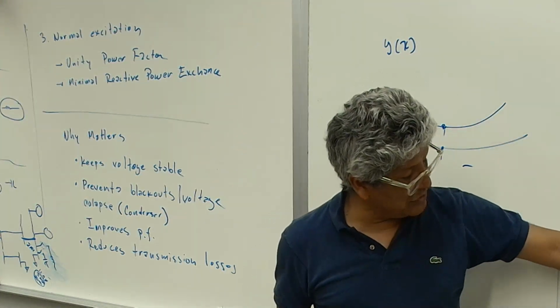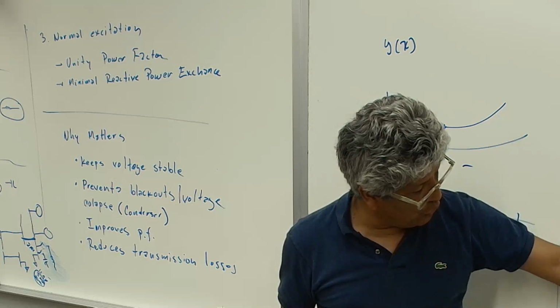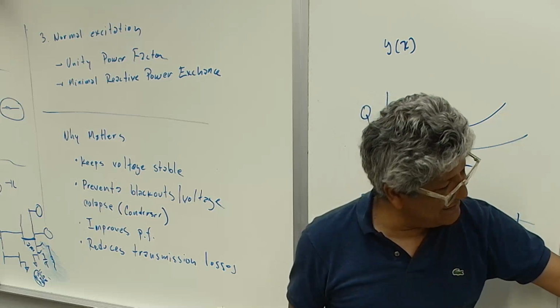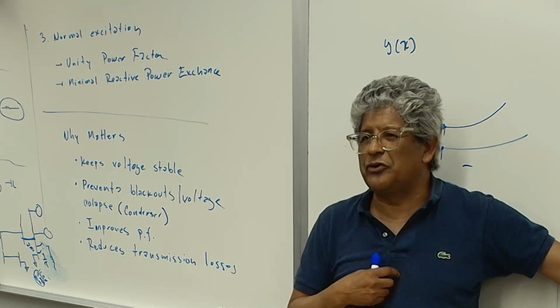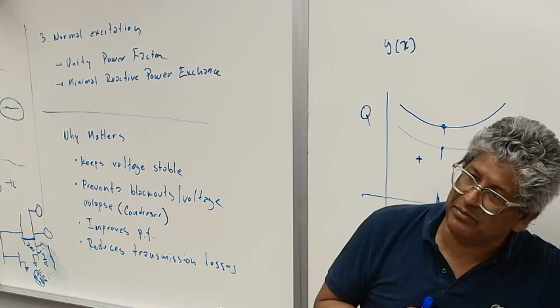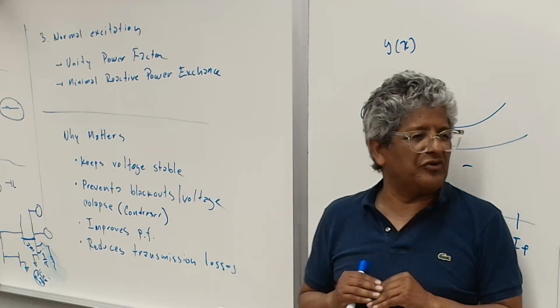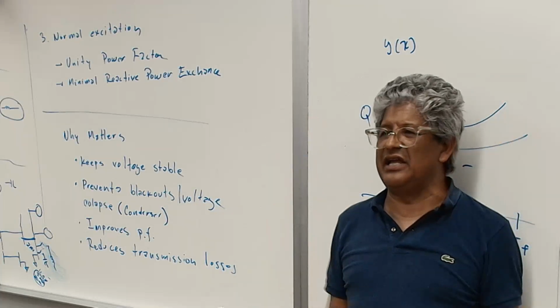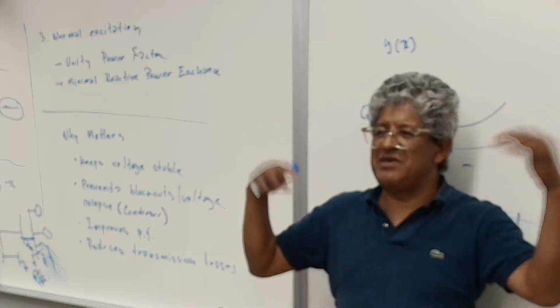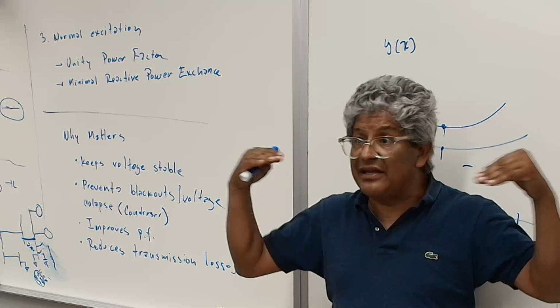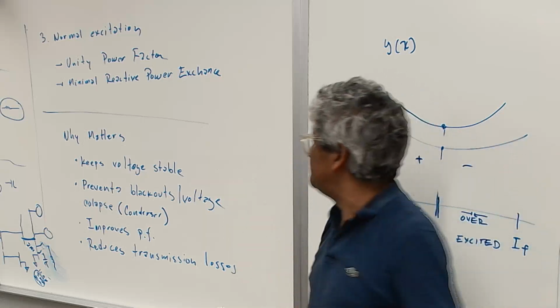Whereas the synchronous machines hold the output until you get to about 0.3 per unit, or 30% of rated voltage, and then they collapse. But by the time you're at 30% of voltage, the system is dead. I mean, you never go there. You go somewhere around maybe 80%. But they have that ability, they can continuously do that.